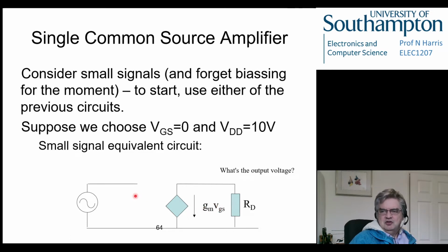So as we vary VGS, we will vary the current through here. And on the input side, remember there's an infinite input impedance to our FET, because that's what we've assumed it is, because it looks like a reverse bias diode. So this doesn't go anywhere, it just sits here. So VGS is the voltage that we're interested in across here. Let me just pull that pen up.